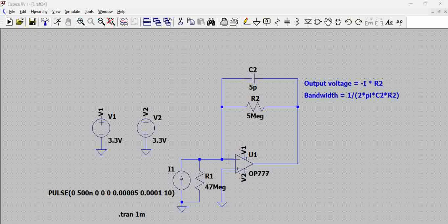And then there will be some pin capacitance. So these two capacitances have to be compensated, and to ensure that there is no distortion or noise that gets introduced, this capacitor is added in the feedback such that we eliminate any noise that is there.